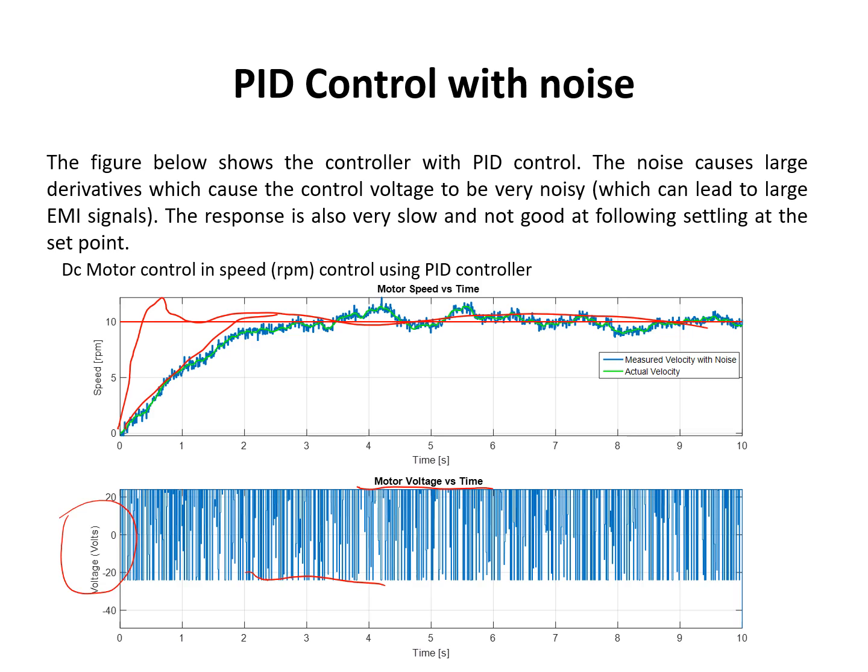And again, this is only really due to the derivative term, which, because we're differentiating, amplifies the noise in our sensor, and we get a very noisy derivative term. As soon as we have any sort of gain, we basically now have a noisy output. So the approach to this is to actually filter the term, which we'll be doing on the next slide.